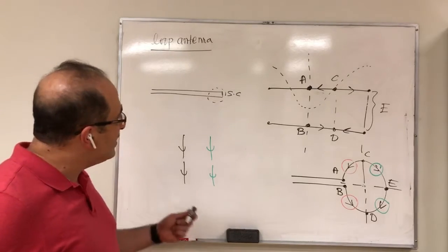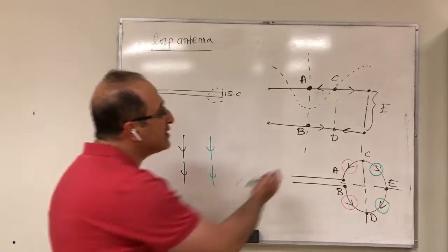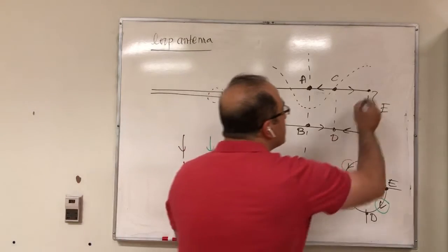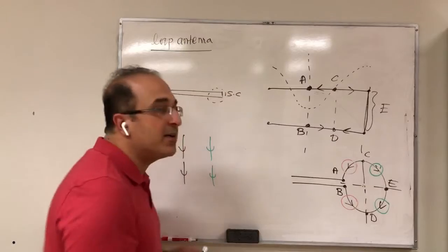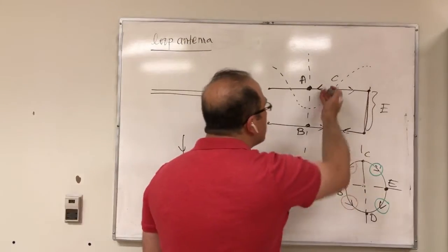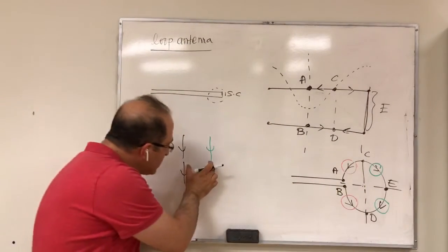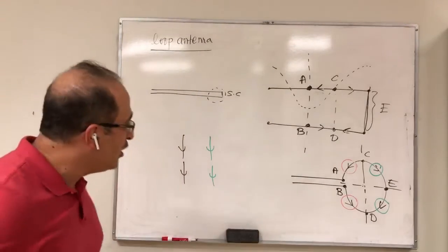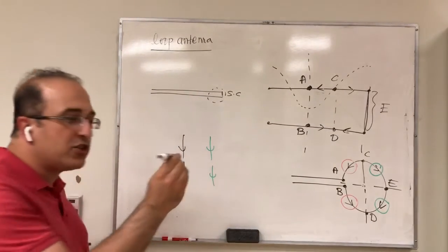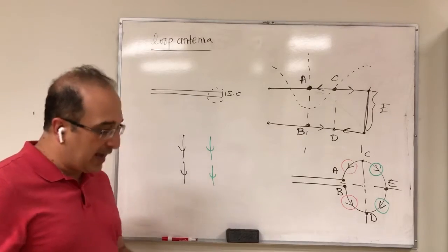So this is very interesting because this short-circuited transmission line tends to cancel everything. This is going to cancel this, this is going to cancel this, but this one is actually, by this trick, now helping you to get maximum radiation when you are along the axis.